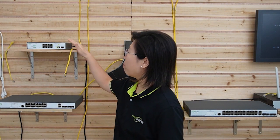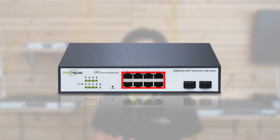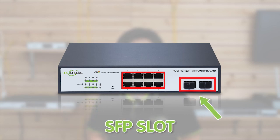At last, we have our 8-port WebSmart PoE switch. It combines the benefits of managed and unmanaged switches. It achieves high performance and efficiency with customized configuration to the network on the concise web interface via easy installation. It has 8 PoE ports and 2 combo ports, also compliant with IEEE 802.3 af and at standards, providing up to 30 watts of power output per port and a total 120 watts power budget. It also provides powerful traffic management, QoS, VLAN, and of course DHCP capabilities.